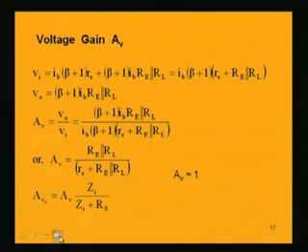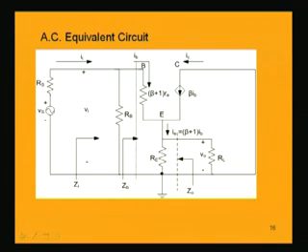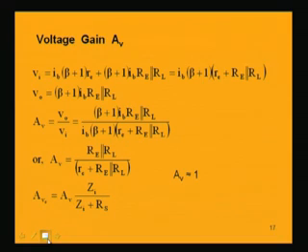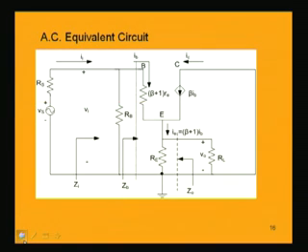And next we go to find out the output impedance and all that. So, after input impedance we will be finding out, again, the voltage gain. Voltage gain is Vo by Vi. Vi we have just now calculated, that is Ib into (beta plus 1) into re plus Re parallel Rl, and Vo, if we look into the circuit, let us find out what this voltage is.